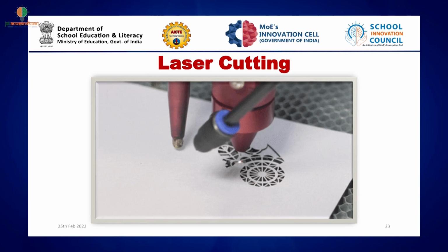There's also a very popular and low cost method which is called laser cutting. This is a flat computer aided cutting of a flatter material like cardboard, thick paper, plywood, or sheet metal, etc. And the cutting is very accurate because it is computer aided. You can create the design on a computer software like Illustrator or Corel Draw, and allow the machine to cut accordingly. You can create 3D assembly of those flat parts.